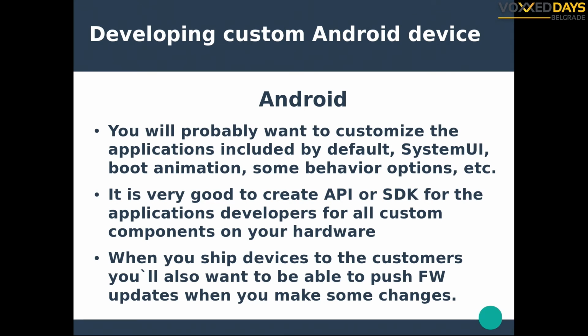As I mentioned, Android will not be aware of how it works on the physical layer. So the good thing would be to create services in Android that will communicate with the kernel, and that will, for example, in this case, turn the LED on and off, and the developer would not have to go to the kernel to open some file descriptor that's controlling the LED. In our case, we had this situation.